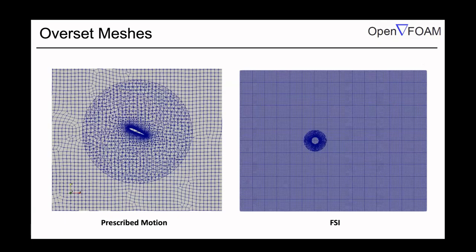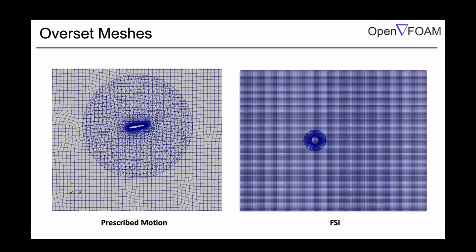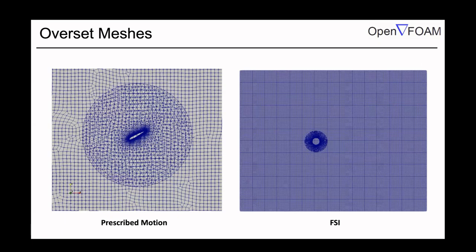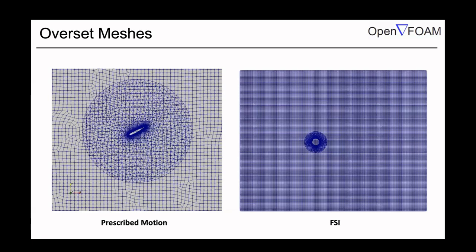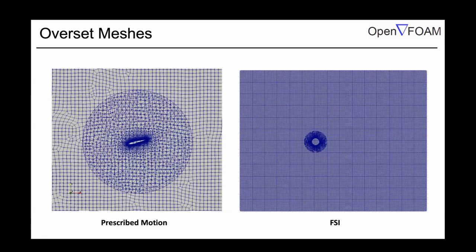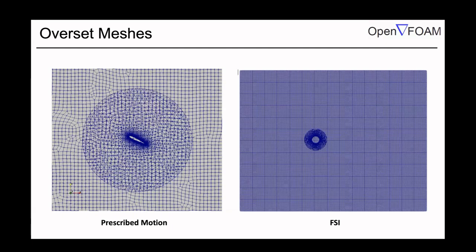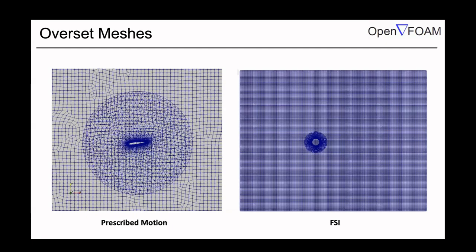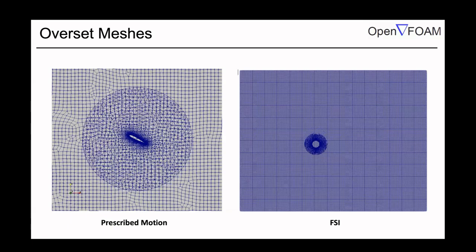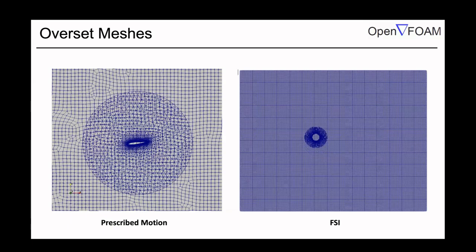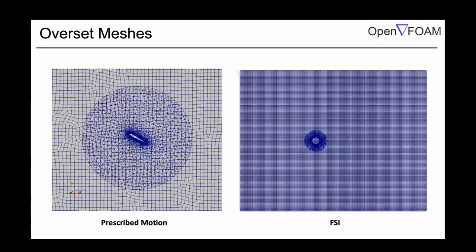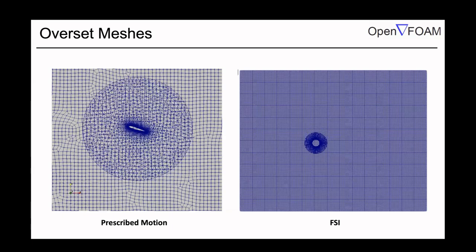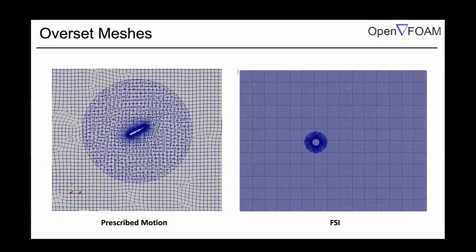And this is basically an example; the prescribed motion I have already shown. Now, if we do that same FSI problem, instead of mesh morphing, we can use the overset method. You see that I do not have any restriction in terms of its kinematics. We can just give any kinematics, any amplitude and frequency, there is no mesh deformation, it will never diverge.